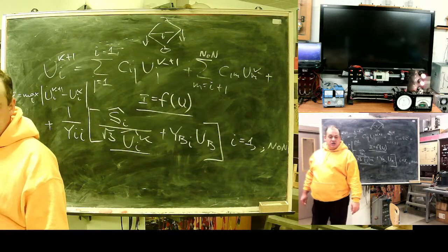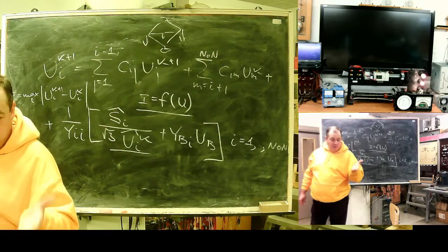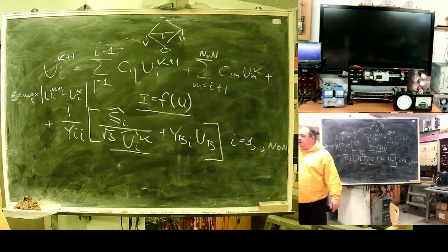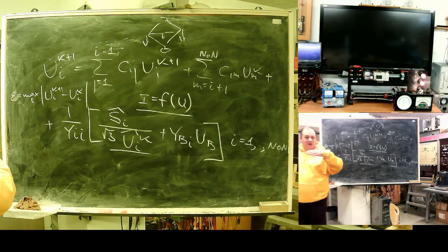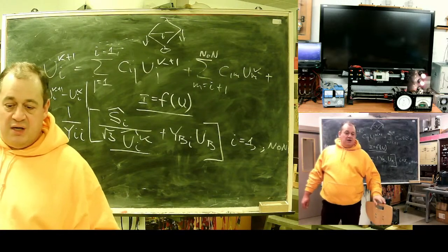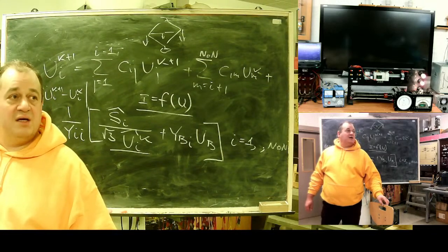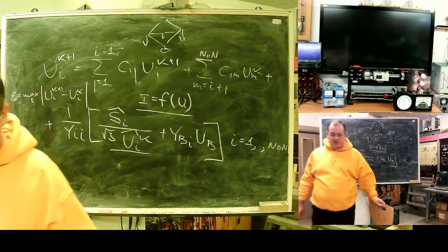Power change should be done better with hydropower plants, they are more suitable for power maneuvering. So one of the power plants or a large system, if we use equivalence, for example, UCTE, the whole UCTE will be a base node or slack bus. English terminology here, correct, is a slack bus. So a powerful power plant, keeping voltage and most importantly power balance.